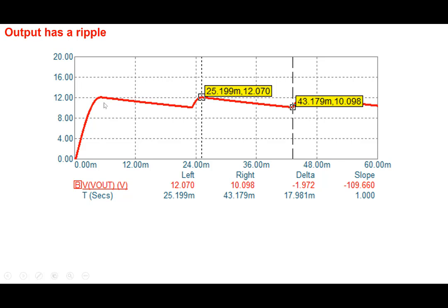So what we note is that we wanted an output which is a DC, but the output has a ripple. We call this the decreasing and then rising and decreasing. We call this a ripple here. And the magnitude of the ripple, if we see that this is VM, the maximum value, and VL is the lowest point of the output voltage here. So we can define ripple voltage VR as VM minus VL, the total variation in the output voltage here.